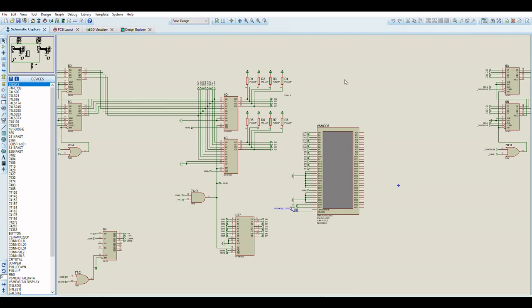The character and tile screens, and actually the Mode 7 screens, were fine with this arrangement because their timing is less precise, but the timing with the sprite update logic was so tight that it would not support 512 pixels. It would not support a horizontal clock at 12 megahertz for the pixels.